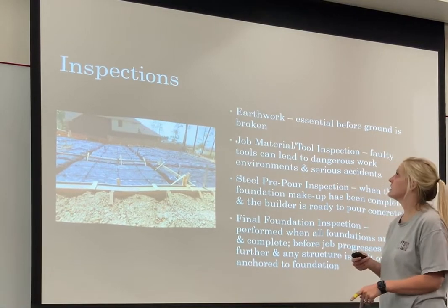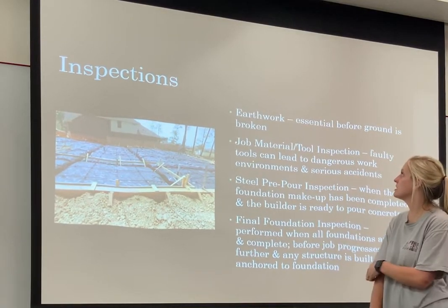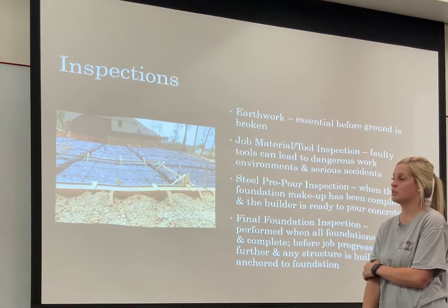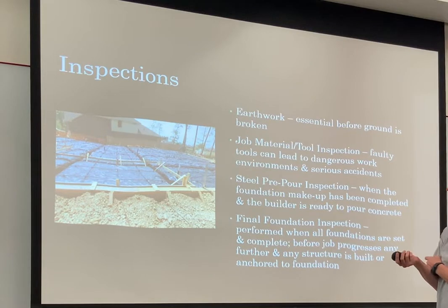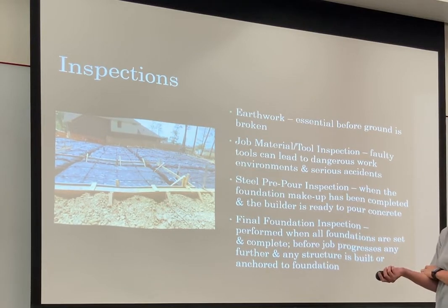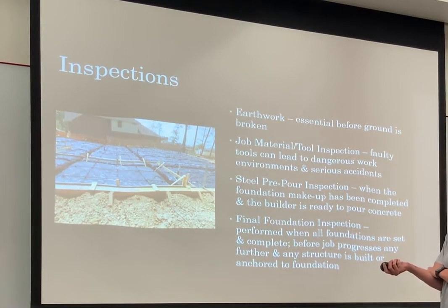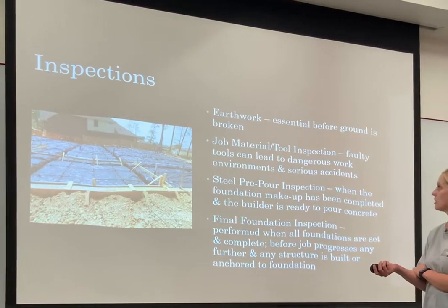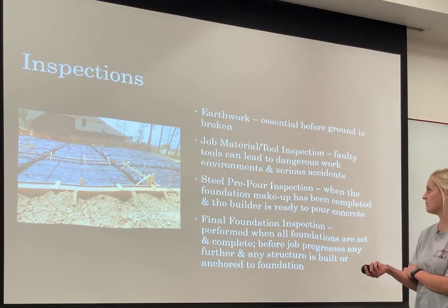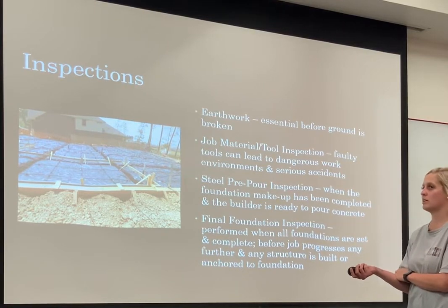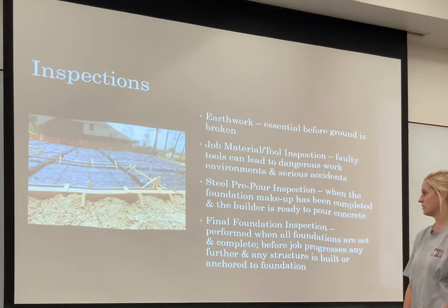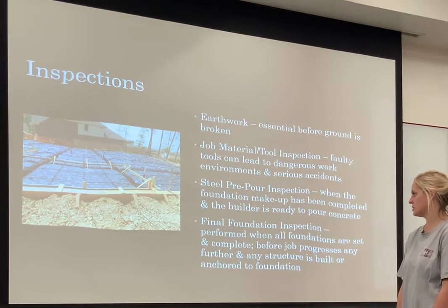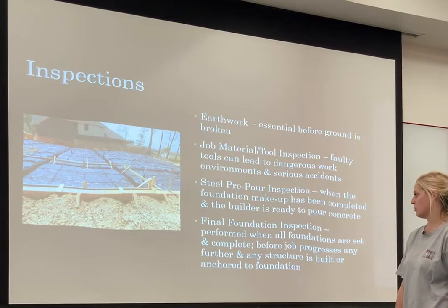Now we're going to talk about inspections. Earthwork inspection is essential before the ground is broken, just to know what soils you're working with. Job materials and tool inspection: faulty tools can lead to dangerous work environments and serious accidents. Steel pre-pour inspection is done when the foundation makeup has been completed and the builder is ready to pour concrete. And final foundation inspection is performed when all foundations are set and complete, which is before the job progresses any further and any structure is built.